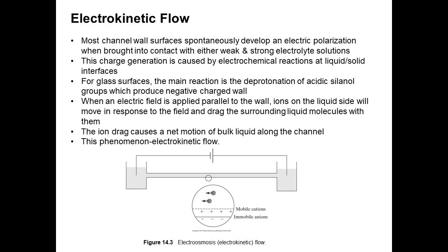For glass surfaces, the main reaction is the deprotonation of acidic silanol groups of the glass, which produces a negative charge wall. When an electrical field is applied parallel to the wall, ions on the liquid side, maybe water, maybe some solutions, will move in response to the field and drag the surrounding liquid molecules with them. The ion drag causes a net motion of bulk liquid along the channel, and this phenomenon is called electrokinetic flow.